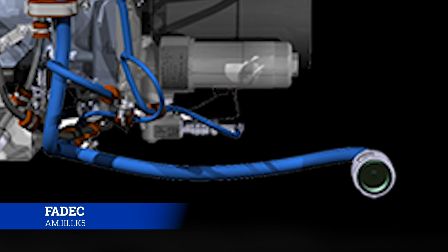Now I've zoomed in on this cylinder. You can see, not the cannon plug that's looking at you, but the first cylinder-looking device that's right there. That is a permanent magnet alternator, a PMA. Basically, it generates electricity if the engine is turning. If the engine continues to turn, it's going to continue to generate electricity, and it's going to generate enough electricity to run the FADEC system. It sits on the opposite side of the starter generator, which is on the right side. That PMA sits there and just continually cranks out electricity to run just the FADEC system, and that's it.